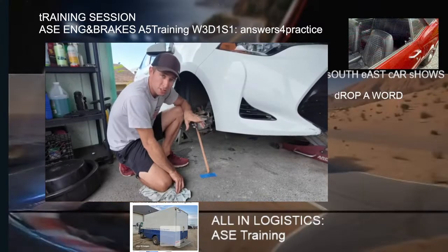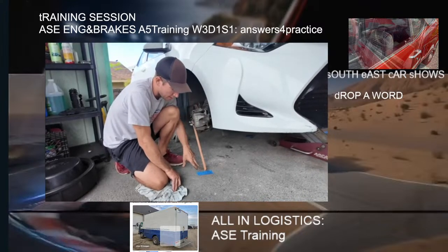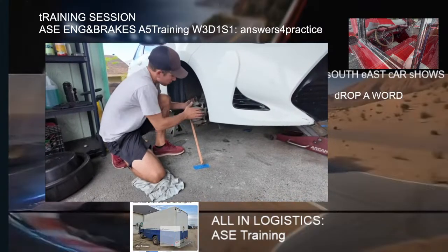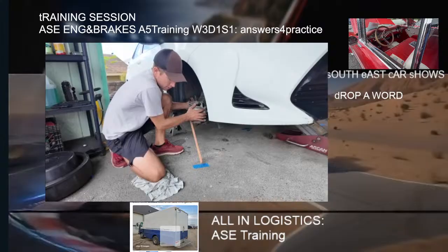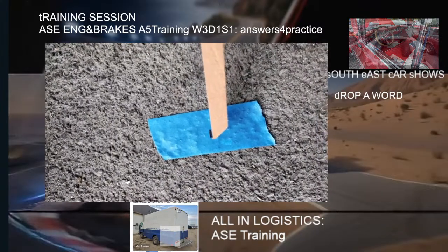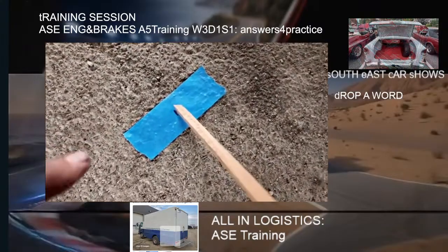As we get ready to readjust the alignment on that left side that we're working on, first we wanna come over to the right side and make sure that this hasn't moved. If it has, you just wanna either turn the steering wheel with a partner, or you can actually sometimes just adjust it here. You wanna get it right back above that line. And back on this left side, before we've even made any adjustments, luckily we're pretty close.